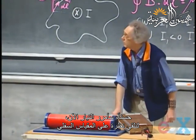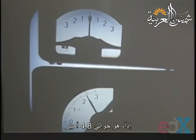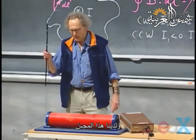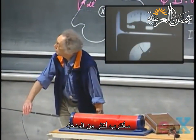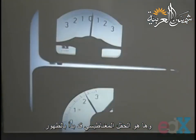So I'm running now a current. Let's look at it. That's the bottom meter. So that is about 4.8 amperes. I assumed it was 4.5. It's a little higher. And here comes this probe. And I'm now about a foot away from the entrance. And you see nothing. And I come closer to the entrance, and the magnetic field begins to show.